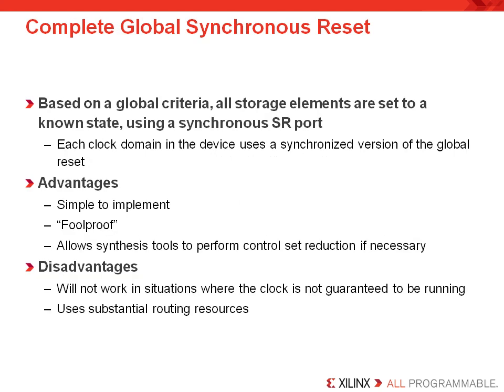Now, the use of a complete global synchronous reset does make very good design sense, and in this case, all storage elements are set to a known state using a synchronous set or reset port. Each clock domain of the device will then use a synchronized version of that global reset. The advantages are that it's easy to implement, it's foolproof, and it allows synthesis tools to perform control set reduction if necessary. But the disadvantages include it not working in situations where the clock is not guaranteed to be running. Also, the other secondary caveat is it uses substantial routing resources.